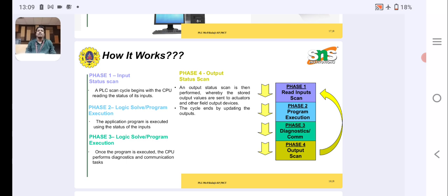Within continuous updating, there is time spent examining each input in turn. The time taken to examine several hundred input output points can be comparatively long. To allow more rapid execution of the program, a specific area of RAM is used to buffer store between the control logic and the input output unit. Each input output has an address in memory.